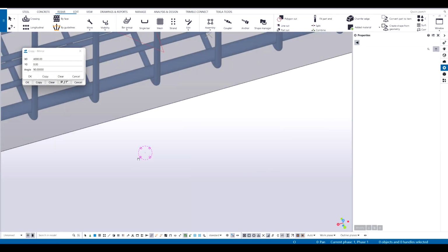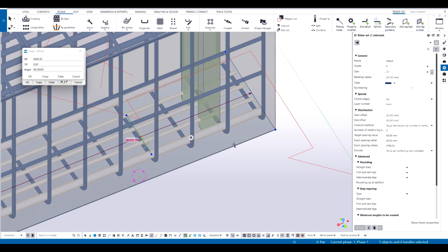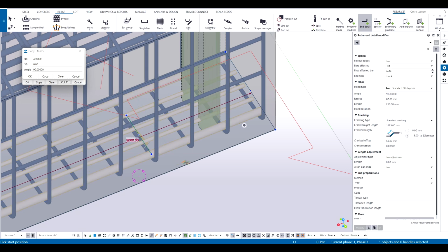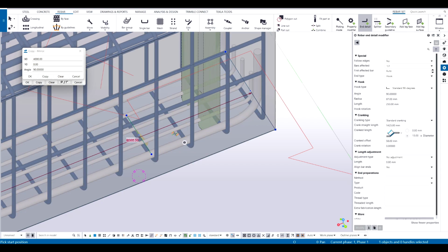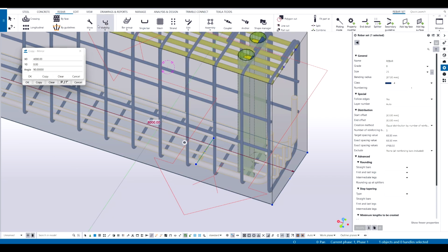So what I can do is, now I go here. If you remember on the rebar groups, you had an option to modify the end, like add a hook here, or add a hook here, or maybe change the cover or length or something like that. That can be done using end detail here. So let's throw an end detail. Now my visibility settings for the rebar sets would hide the end detail thing. Now you see all the bars have a hook here. So yeah, a hook here. Let's turn on the end detail thing.